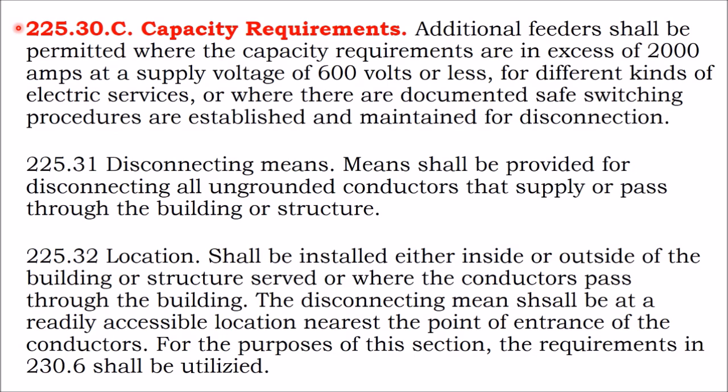Well, how much is that? 2,000 amps times 208 volts, or let's say 480 volts. That's almost 10 megawatts of power per service. So when you get into extremely large capacity requirements, you're dealing with a lot of power.